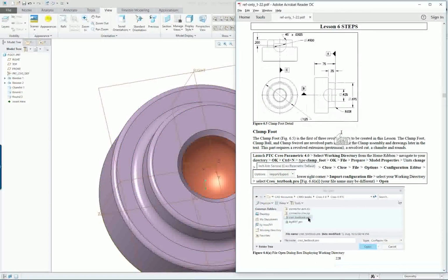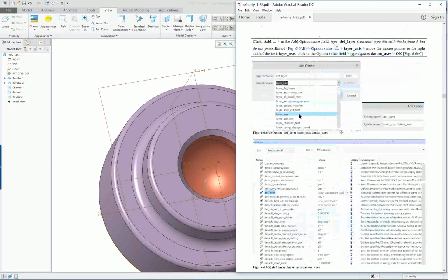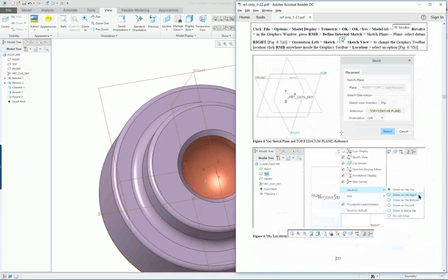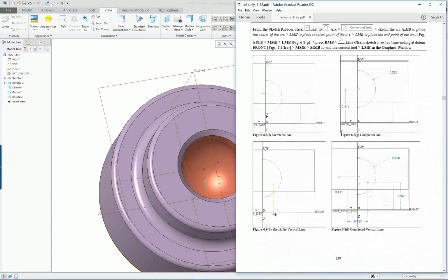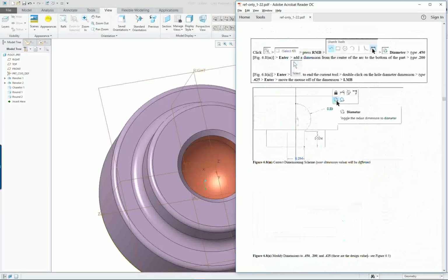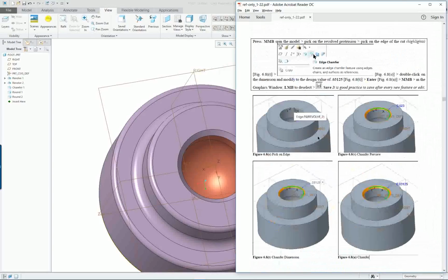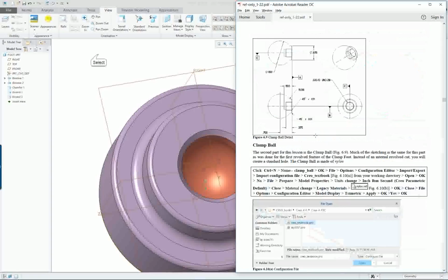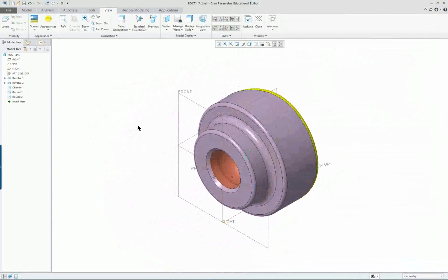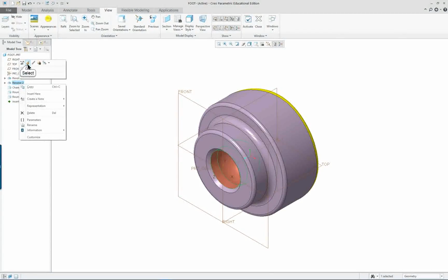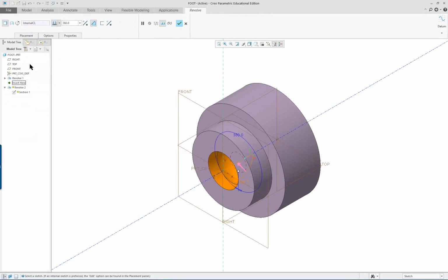This particular project is important that you save that section, because if it's not available in the next part that we do, the next Revolve feature, you're going to have to go back and save it. And I should actually probably do that for you right here. We'll demo it. So let's say you get to the next project and you forgot to save that section. So we simply are going to go in here and edit the definition of it. So you can open this part up again if you need to.